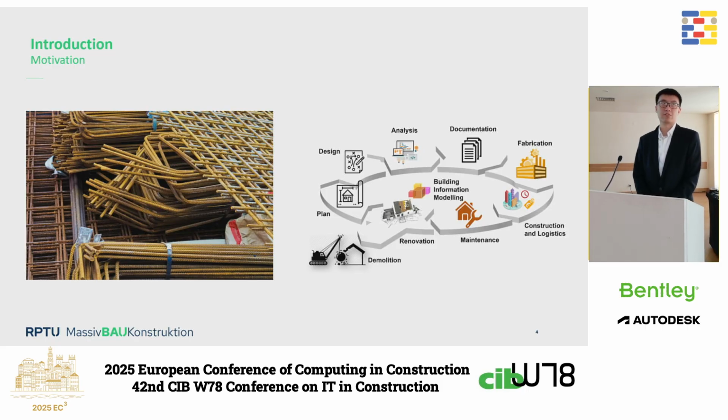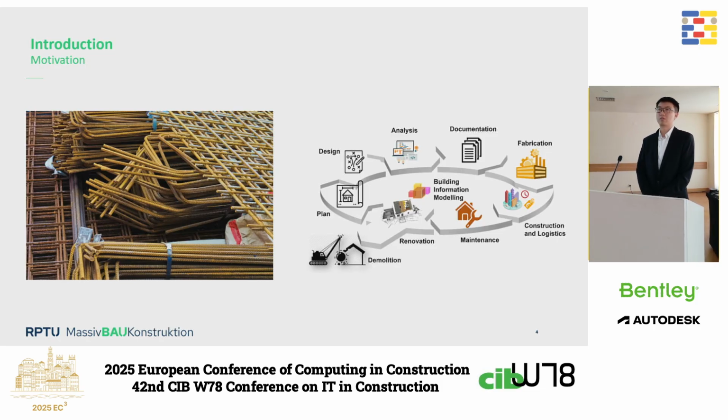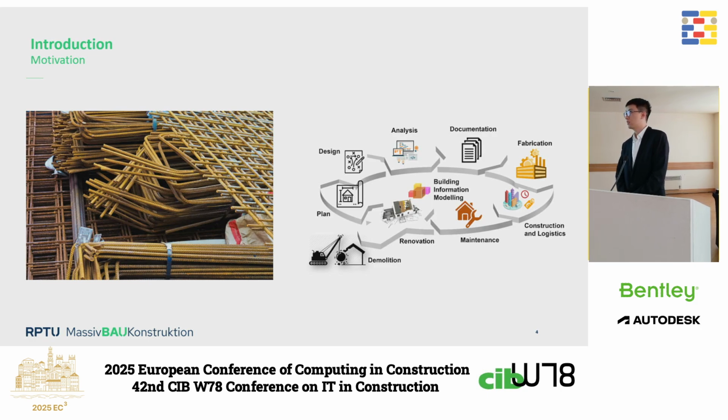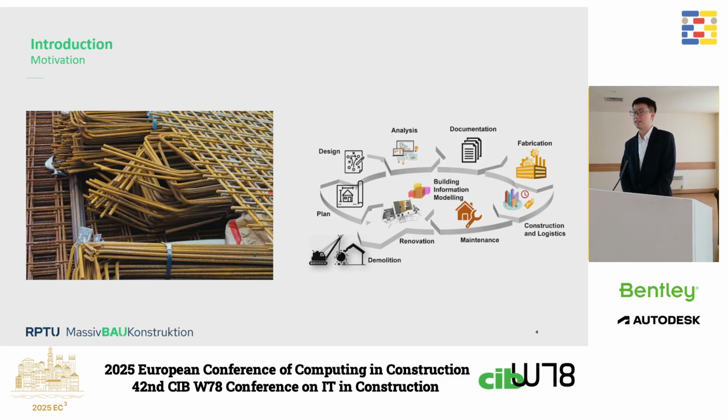In our study we use 2 devices with GPR technology. One is the Hilti PS1000 and the other is the GP8000 from Proceq. So the process includes scanning. We should first scan the concrete plates, and then we do data processing, and finally we make the reconstruction.